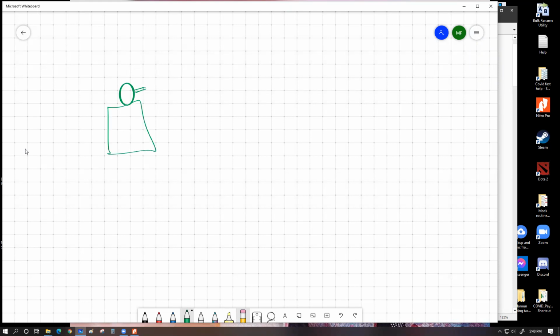If we do not use the charge, let's say the not paint, let's say I'm drawing it with blue. It makes an angle of this much. This is the angle of spread for spraying without the use of static electricity, where the positive end is not connected. But the moment we connect it to the positive terminal of a certain DC source, battery or DC source, then those paint droplets themselves will become positively charged. So essentially, they would tend to spread out more.